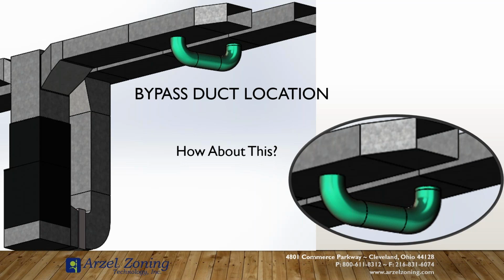On your return side, this is going to give you a point that may be subject to the maximum draw, depending upon how your returns are laid out. This may be a more medium draw, but we're giving those BTUs a chance to diffuse into the home before we dump it back through our bypass. And now when we dump it into our return, we're giving it a much greater length of duct to mingle with the air from the home coming back into the furnace. So it tempers it, and we have a less extreme temperature overheating our return air.